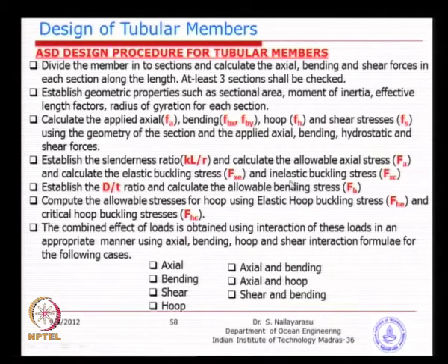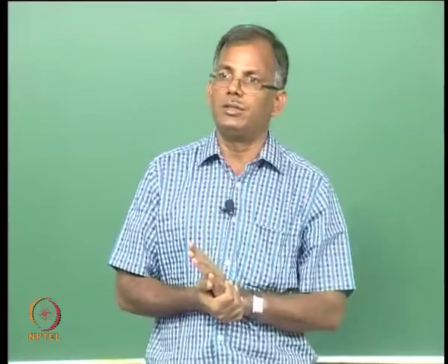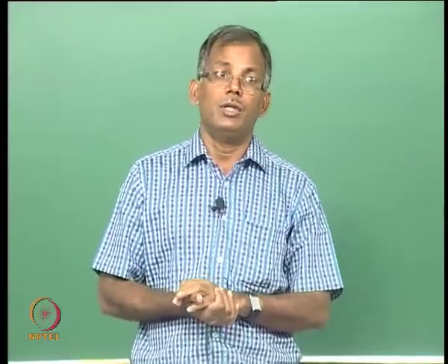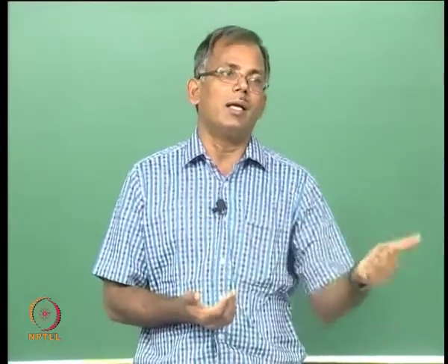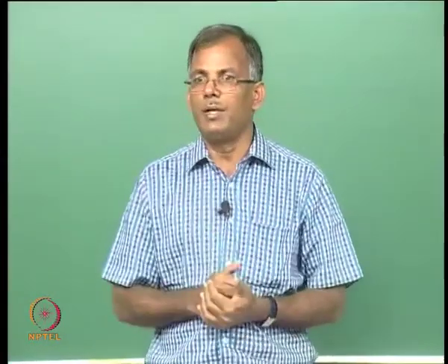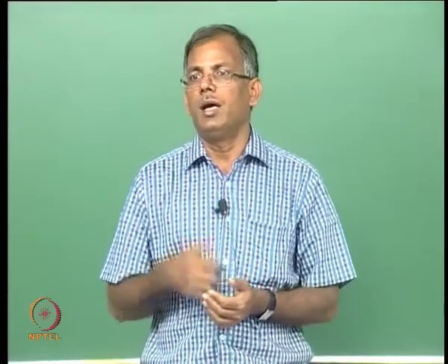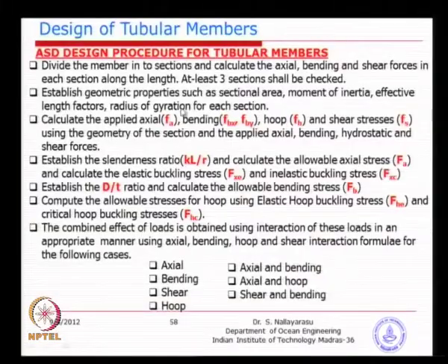axial direction. So, what we normally do is calculate the allowable stress using the normal yield stress and then evaluate whether yielding is going to happen or buckling is going to happen even before that. That means limiting the yield stress to the buckling stress. So, the limiting yield stress is nothing but the maximum stress at which buckling occurs. Here we have two types of buckling, one is local buckling, the other is global buckling. Global buckling is taken care of in terms of Euler buckling length, which is a K factor, but the local buckling has not been taken into account. So, that is what we are going to look at.